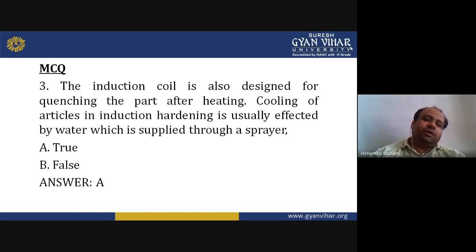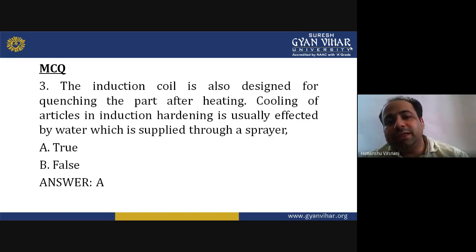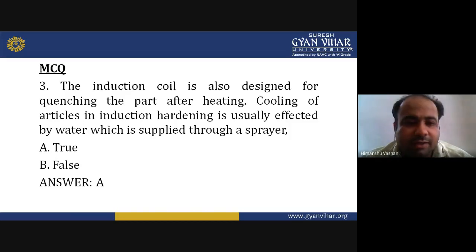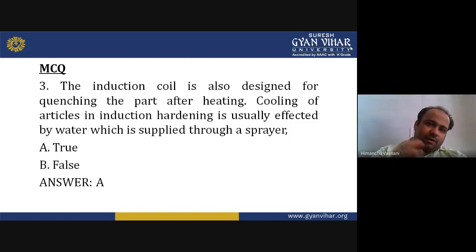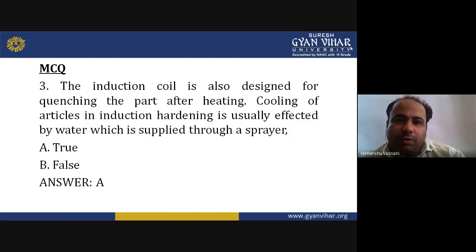Induction coil is also designed for quenching the part after heating. The cooling of articles in induction hardening is usually effected by water which is supplied through a sprayer. If you remember the diagram that I have shown you in induction heating, you can easily understand that the diagram was also having a sprayer at the bottom.